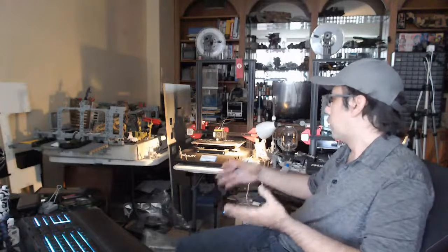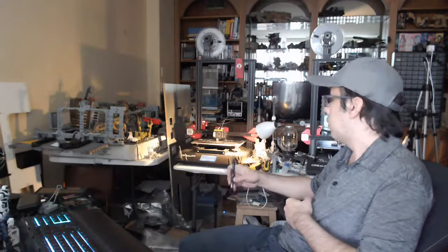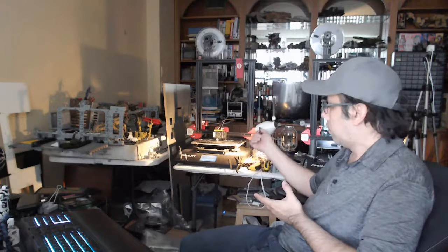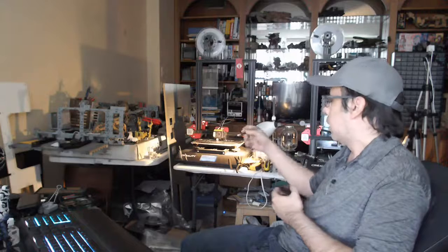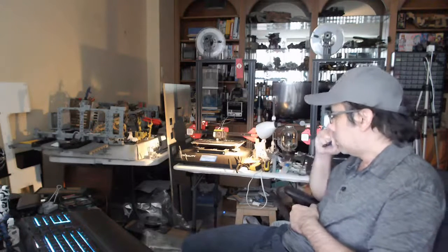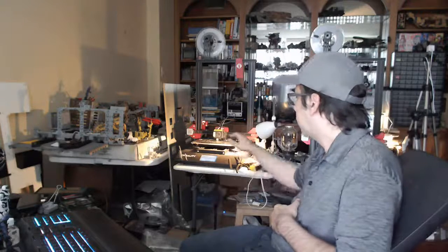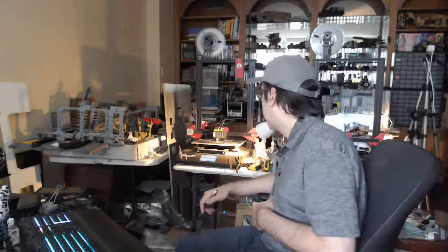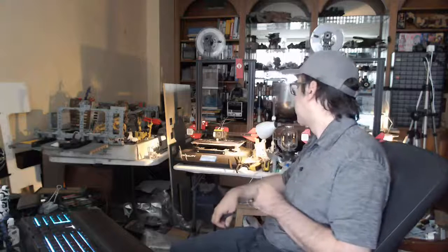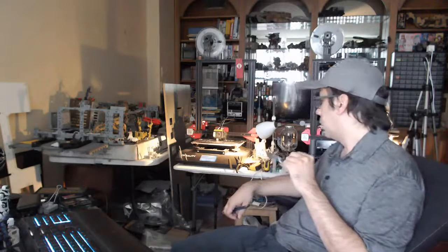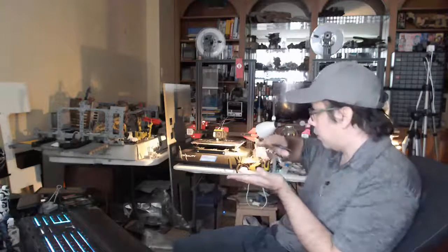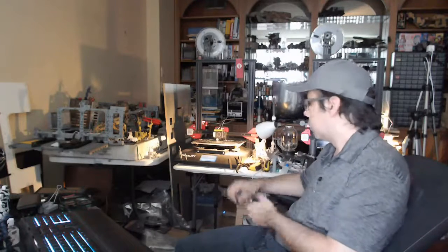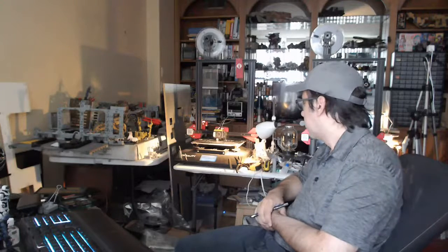When you turn on the machine, even though I did the calibration just now, it's still going to be a little bit off. So you'll see me at the very beginning of each print keep a watchful eye, and if the plastic starts to not stick to the build plate, you'll see me manually lowering the extruder just a little bit until it does.